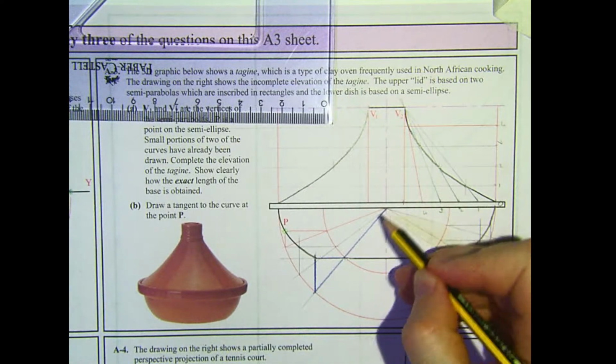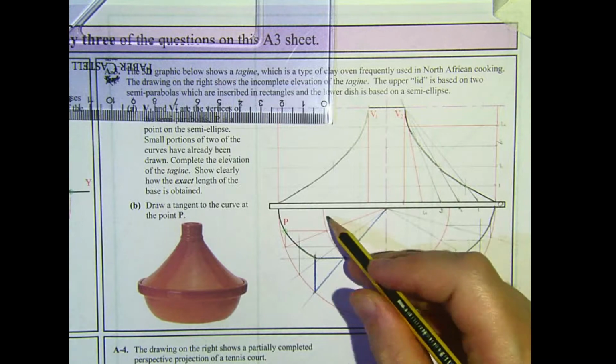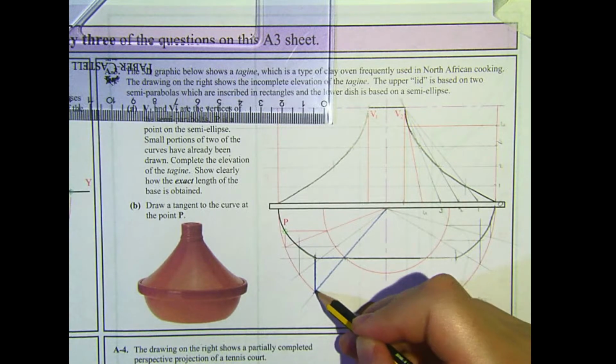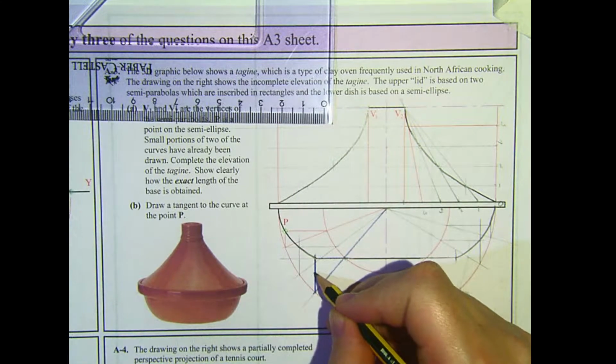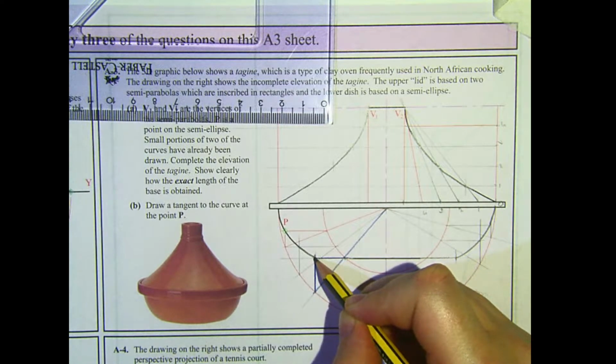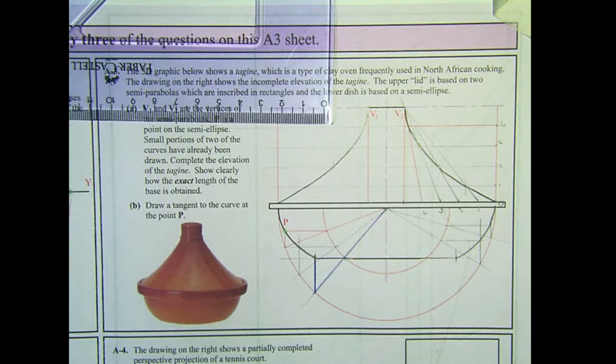So point from the center out through this point here where that horizontal line intersects the minor auxiliary circle. That's this blue line coming down this way. Where that cuts the major auxiliary circle, we're going to go perpendicular to the major axis. That's already coming across here, so that gives us this exact point where that transitions, where it changes from the base to the horizontal line.